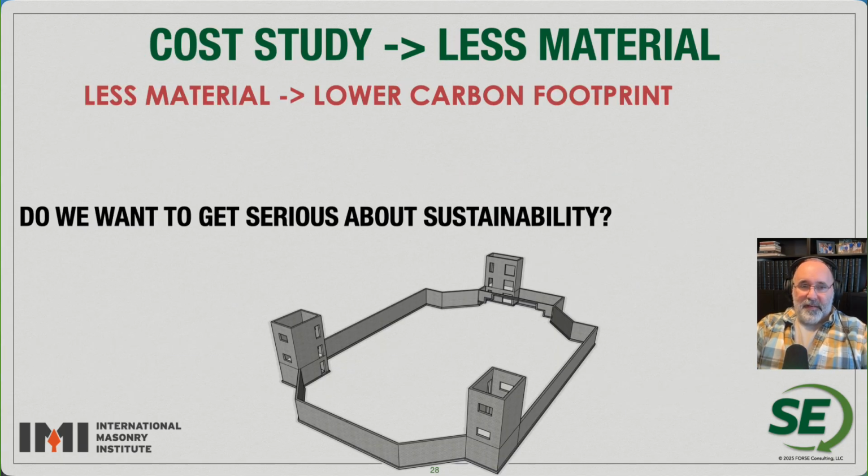So again, the masonry that we're using is certainly a lot less material. And I think if anybody is really serious about sustainability and lowering the carbon footprint, and they haven't done masonry foundation walls, I really don't think they're that serious, because it's a very obvious and easy way to get some very good savings for your design. We can really lower our carbon footprint pretty quickly just by switching to concrete masonry instead of a concrete basement wall.